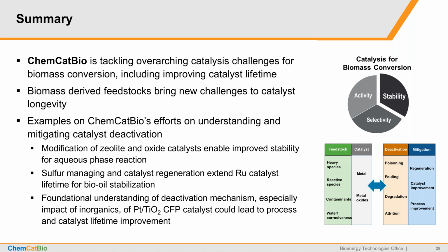I hope I showed you examples of ChemCatBio's efforts on understanding and mitigating catalytic degradation, especially how we are modifying zeolite and oxide catalysts to enable improved stability for aqueous phase reactions. How are we managing sulfur, or developing a catalyst regeneration protocol to extend the ruthenium catalyst lifetime for biostabilization? And how are we conducting foundational understanding of the deactivation mechanism of palladium-titanium catalysts for catalytic pyrolysis, which could lead to process and catalyst improvement.